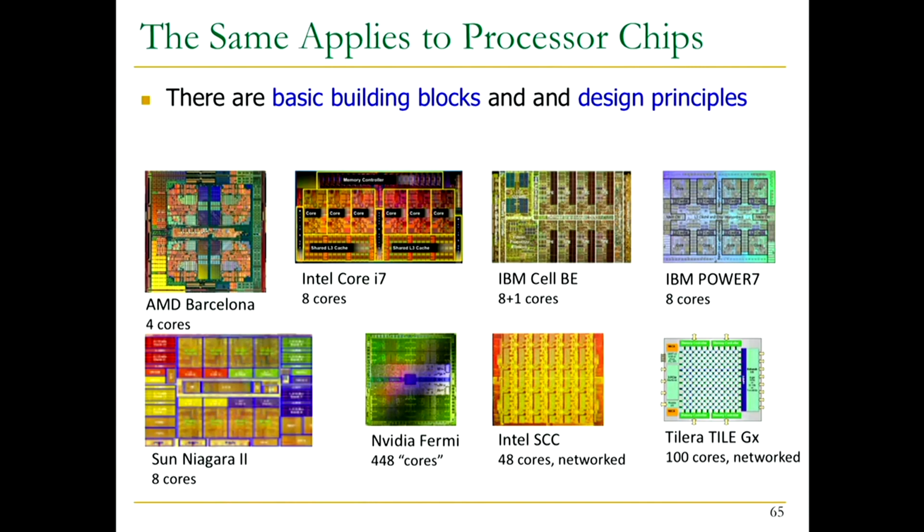And if you're receiving packets at 100 gigabits per second, let's say, you can process them that fast. Whereas if you take those packets and try to encrypt and decrypt them in a core that looks like this, that's not specialized, that's very general purpose, it takes much more energy and it may not even meet your bandwidth requirements, which is 100 gigabits per second. Right? So basically they put a cryptographic engine over here that processes packets in a very specialized manner.